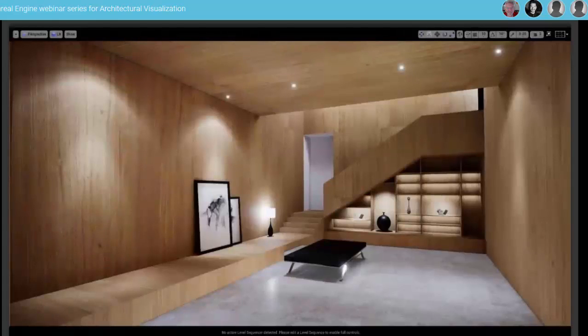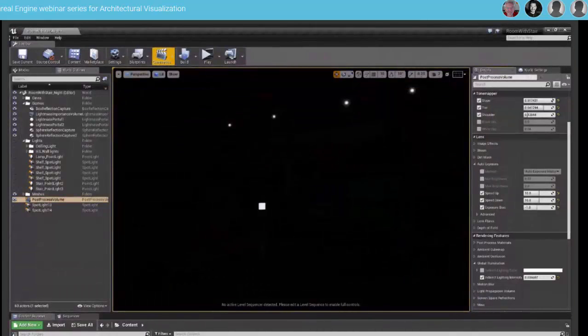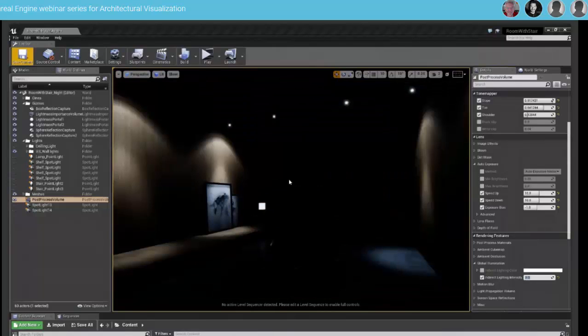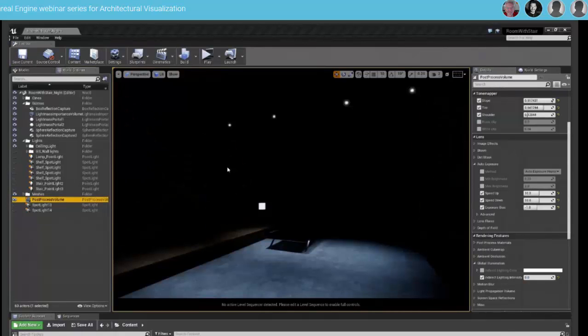So let me just build up zero light here. And I've just bumped up my indirect lighting intensity here. So this is the result of the Lightmass calculation, just very, very subtle. These are my IES lights, so I've brought them close to the wall and then worked with an IES value. That's really straightforward to bring in. And then these are my ceiling lights going straight down.